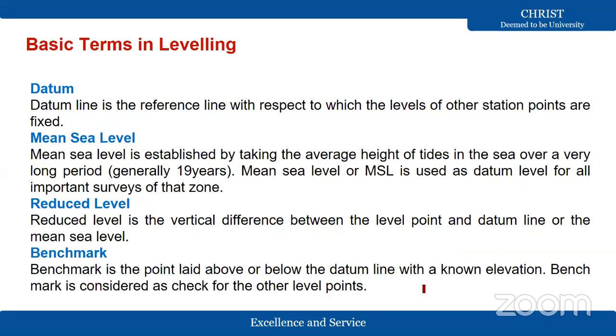Again, a benchmark is a point laid above or below the datum line with a known elevation mark, and it is considered a check for the other leveling points. At least one benchmark is required to establish your network of control points for the Z dimension, that is, leveling. If you don't have any benchmark established by Survey of India in your area, then for important surveys we need to transfer a benchmark from other areas, nearby villages or somewhere.